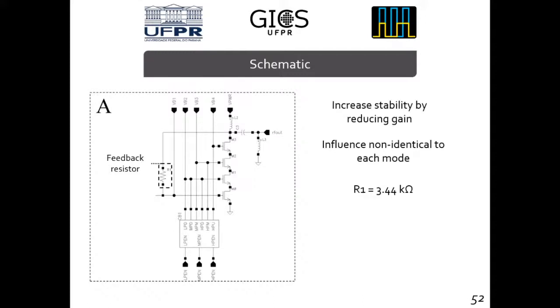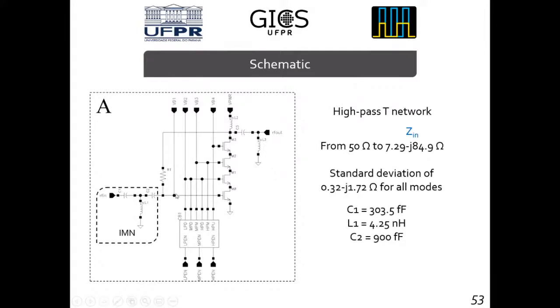I think that something is missing, because we see the feedback resistor between the drain and the gate. But you also need a capacitance in series with the resistor, no? Because if you forget the capacitance, you will have a problem of bias between the drain bias and the gate bias.